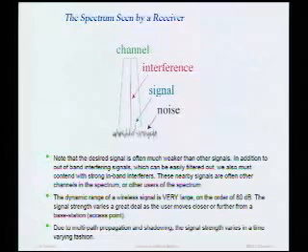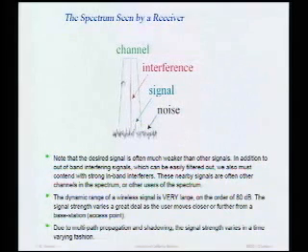I'm saying that there's a lot of noise and junk that comes with the signal, too. So if you just use an amplifier right away, you're just going to be amplifying the other stuff, too. That's right. That's precisely right. So as I've shown in this picture here, you can see that in general you have a channel. The channel is a frequency span over which you're communicating, and this little spike here is your signal. I'm not sure if it shows up very clearly there. And you might have a huge interferer sitting right next to you.